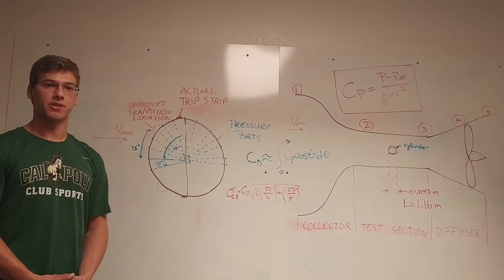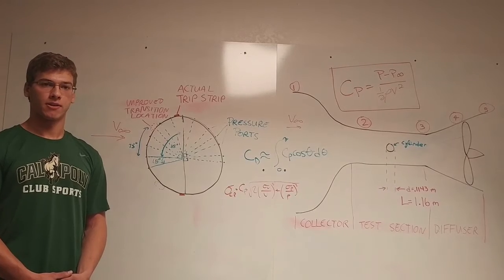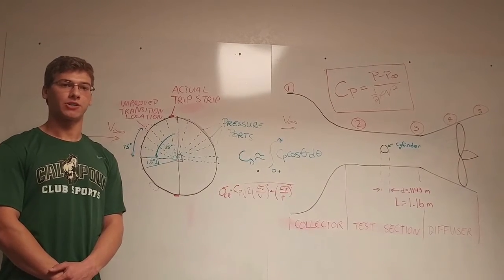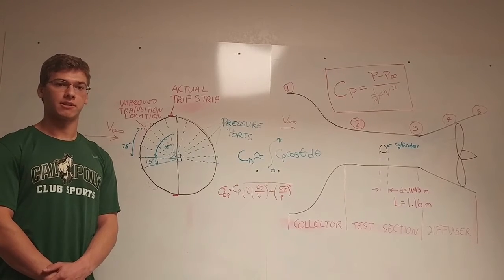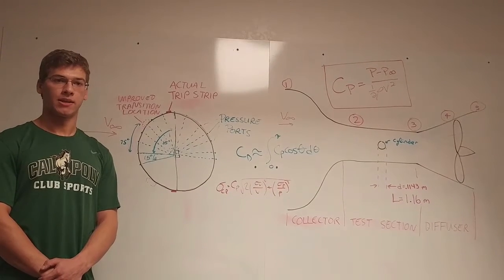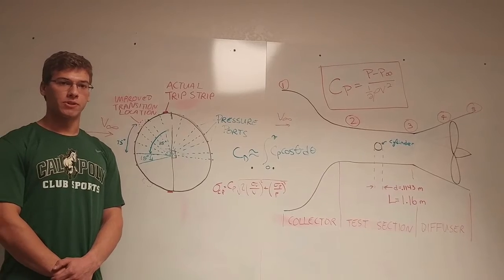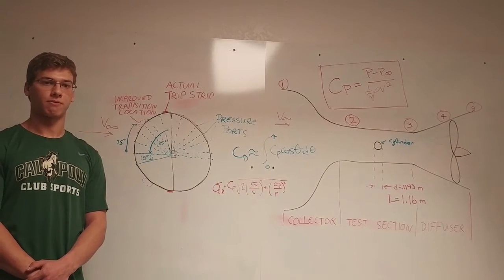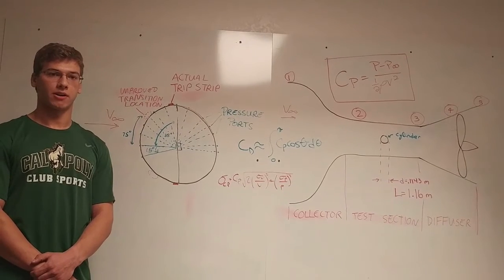It is also important to understand propagation of error in our calculations. With this scenario, we will use standard deviation as a measure of variation and uncertainty. Because we are assuming density to be nearly constant, we will not propagate uncertainty in this variable. However, we do have existing standard deviations for our static pressure readings, as well as for our free stream velocities, which are squared in the denominator of this equation.